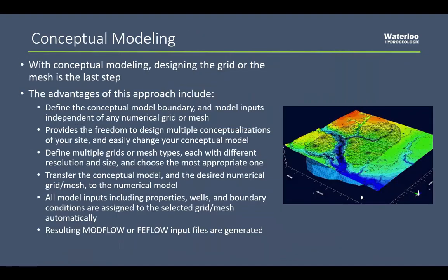Now with the conceptual modeling approach in Visual MODFLOW Flex, you define the conceptual model boundary and all model inputs completely independent of any numerical grid. And then you can design as many different grids as you want. You can design multiple finite difference grids, multiple MODFLOW USG grids, both Voronoi grids and Q grids. You can create a few FEFLOW meshes, and then based all on the one single conceptual model, you can quickly and easily convert that conceptual model to 5 or 6 individual instances of your numerical model with different grids.